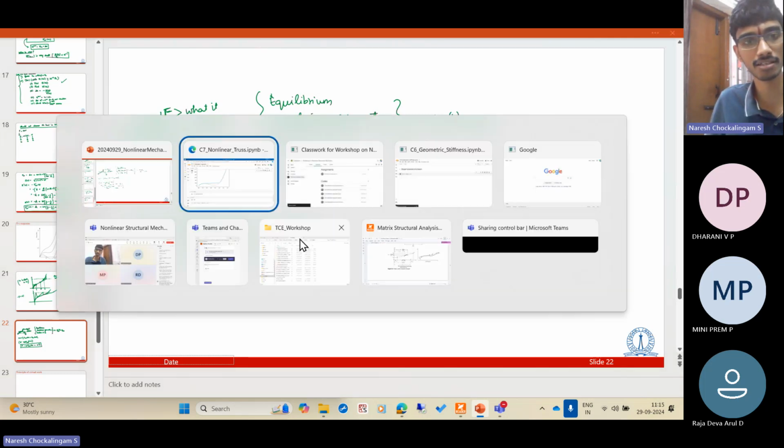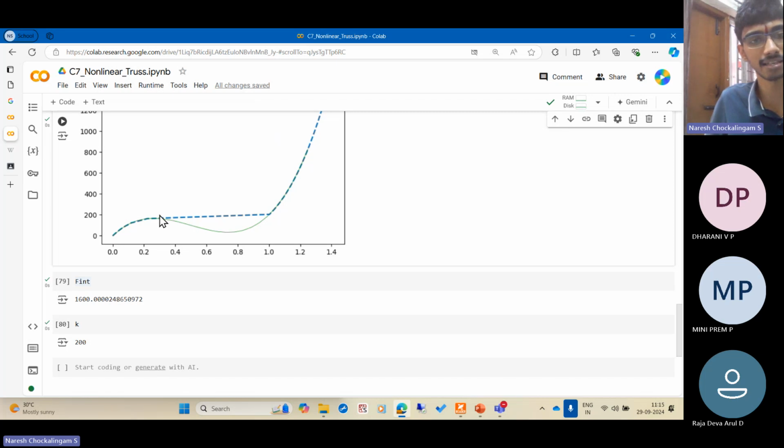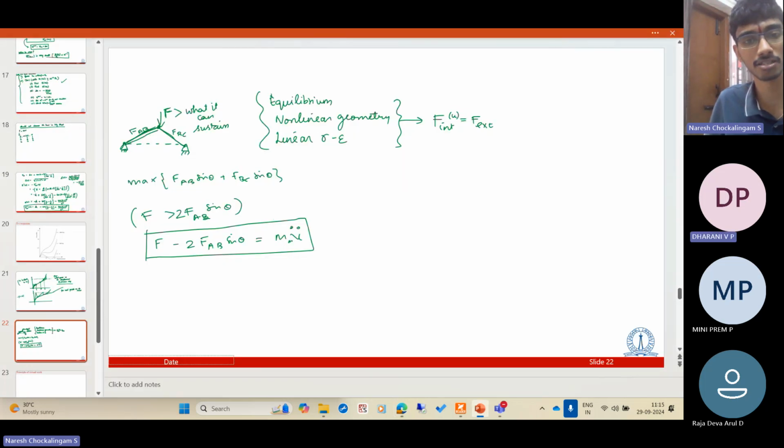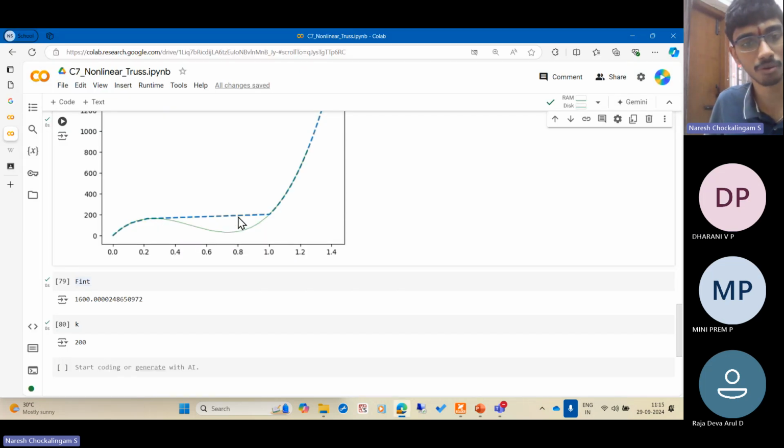It will undergo an acceleration, but it will not accelerate indefinitely. It will accelerate and go to this configuration. Once it goes to that configuration, from there again you can keep increasing the force. So that is what will happen. It is true, in reality the structure will accelerate, but what we got just here is not a dynamic solution. It is just that the static solver is not able to find any nearby point, so it is finding the next point, which is here. But in reality, the path it takes from this limit point to this point will be an accelerated solution.